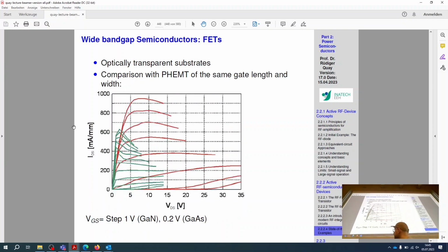Comparison of GaN and GaAs, as we said. Why GaN? GaN is a higher bandgap material. It allows a higher breakdown voltage. Applying more voltage versus applying a lower voltage, even though the carrier mobility of GaAs is far higher than the carrier mobility of GaN, still, the carrier mobility, the band gap, the crystal structure and all that are intrinsic properties of the material.